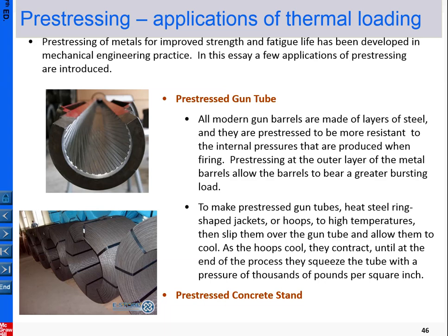One typical application for thermal stress is, for example, here we call this the gun barrel. So the gun barrel, basically inside is a material, outside is another material. We want to pre-stress the barrel here to reinforce the capacity of carrying exploded force. So the question is how the manufacturers pre-stress such a core sleeved inside another material. And you can read the detail here, and I can use the following examples to demonstrate this concept.